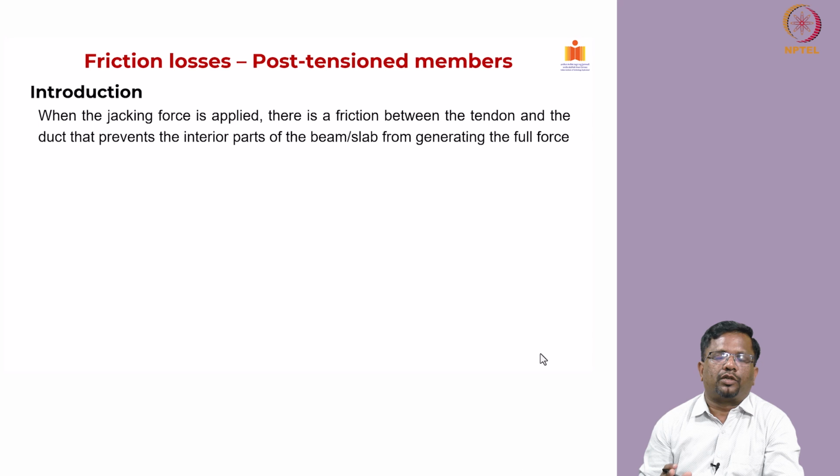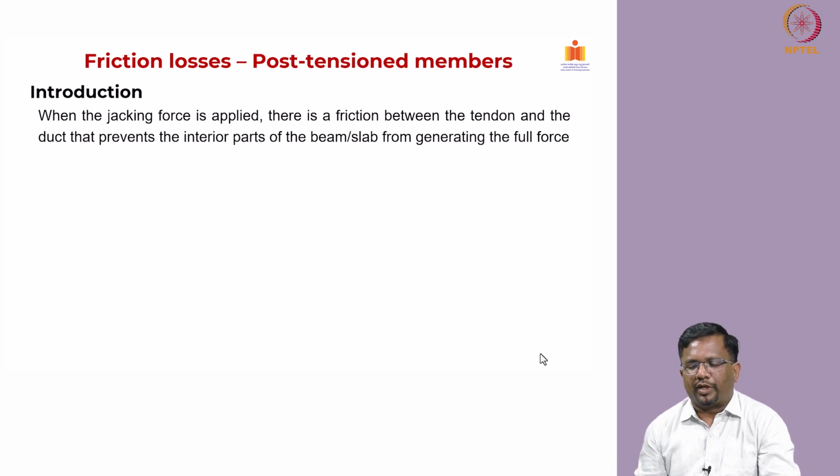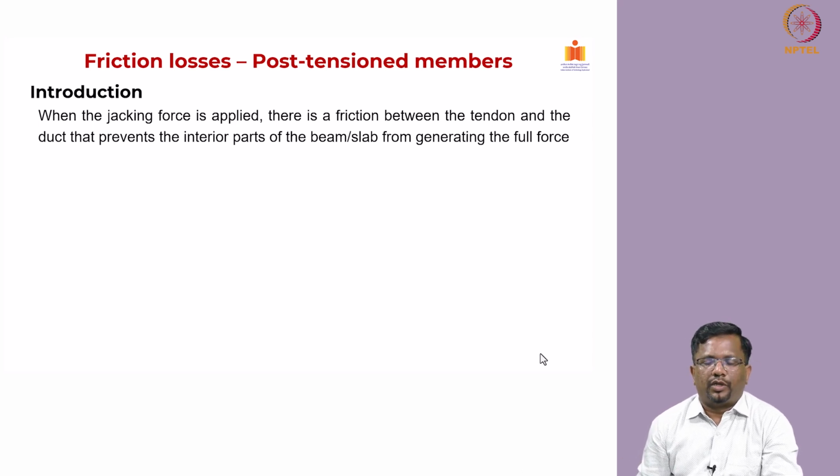So far we have talked about elastic shortening. Now we are getting into the friction losses. Now what is a friction loss? When the jacking force is applied, there is going to be a friction between the tendon and the duct, right?